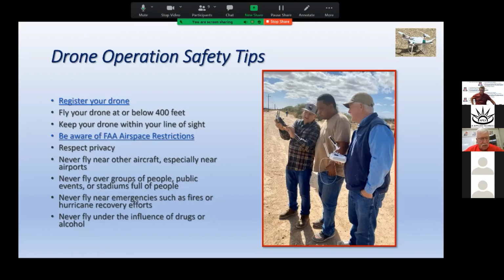We've seen people do this, and they're most likely ignorant of the law, thinking that they can do that or they're not going to get in trouble. If somebody asks to fly a drone over a concert and wants to drop things from it, like golf balls, which pose a hazard, obviously they're going to be discouraged from doing that. They're going to be in violation. There is a waiver right now that the FAA is addressing for flying over groups of people, but typically the only people you can fly over are those associated with the operation of the drone.